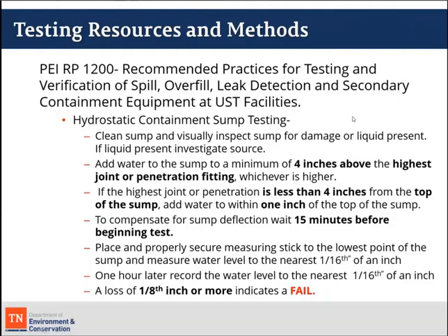So initially, you want to make sure that the sump is clean, especially with the disposal of sump water. That's a big sticky subject with the hydrostatic test method: what are we going to do with this contaminated test water, taking it from site to site, and disposal of that? So you want to minimize the contamination of your test water as much as possible by making sure that your sump is clean and you've removed as much petroleum residue as you can before filling it full of water.